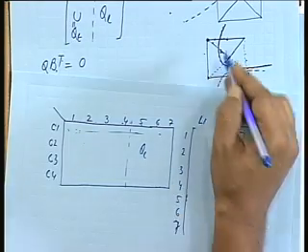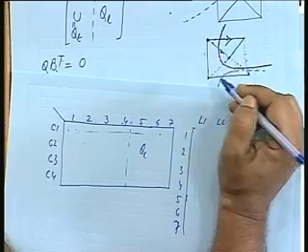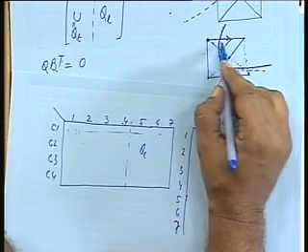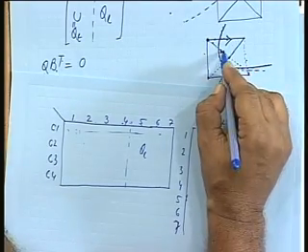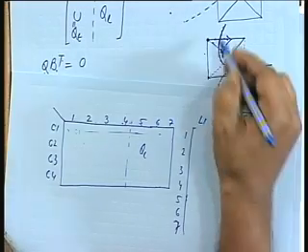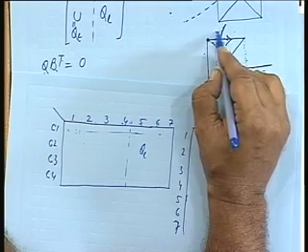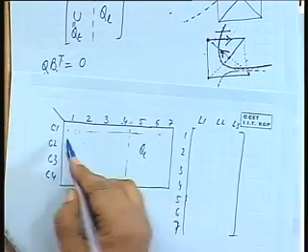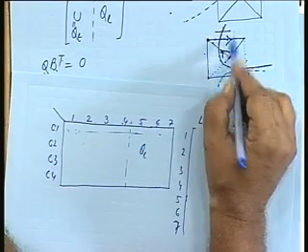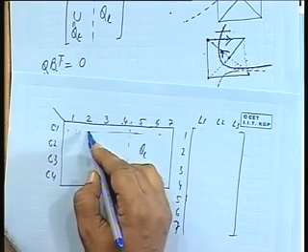And now you see the direction of the cut set. For example, suppose this is the direction of the tree element, and suppose this is the element of the link, then the cut set direction is taken as the direction of the twig. So the cut set direction is this. So for the cut set, this is plus, this is minus, next element is minus.